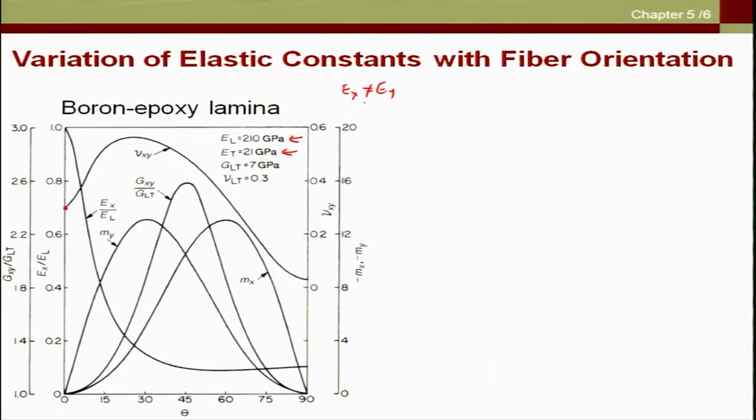Ex in general is not equal to Ey, and we can also say that nu xy is not equal to nu yx, and all this is happening because El is not equal to Et and nu Lt is not equal to nu Tl.